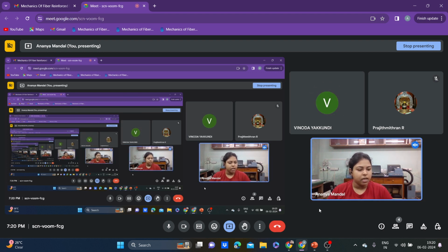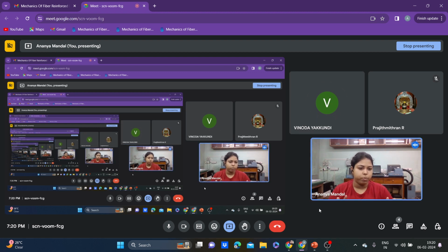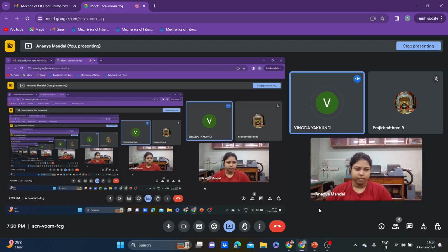I work on filament winding. There, 0.4 we assume as normal and a very good product, if we get a fiber volume fraction of 0.4. Okay, ma'am. I am also working with prepreg, and in prepreg we are making the laminate. So there is 50% fiber volume fraction and 50% resin. We have done two types, and some properties are changeable.